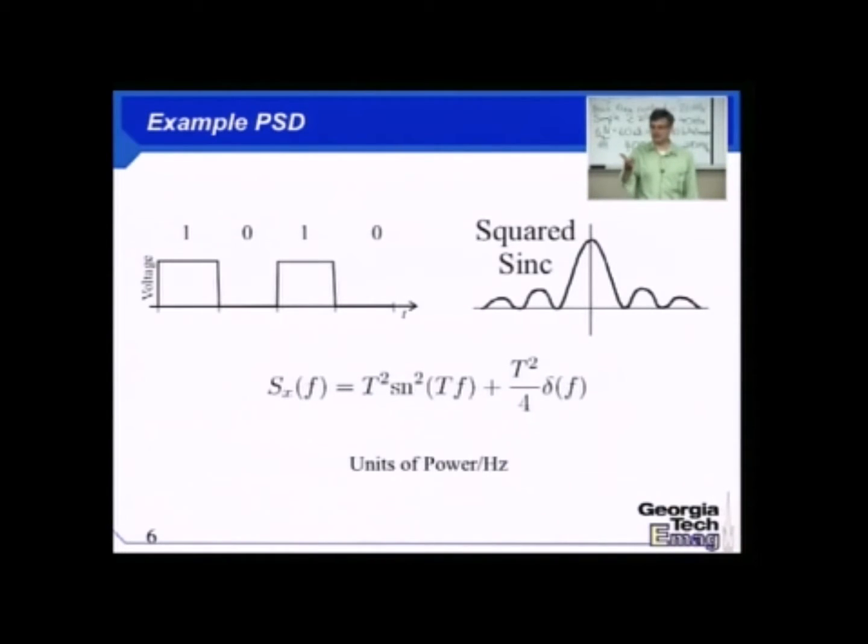Why? Because the support theorem, when we studied it in antennas, said that if I start with a finite support pulse in the time domain, my frequency domain has to have infinite support. And in fact, the less support I provide in the time domain, the more high-frequency components I'm going to have. You can show that pretty easily as well.